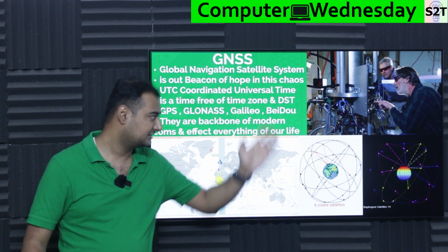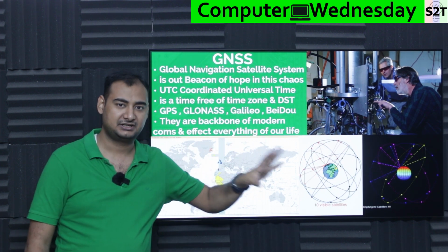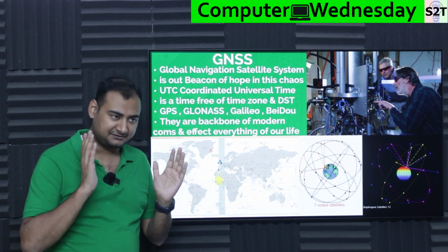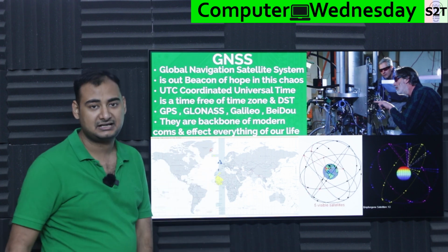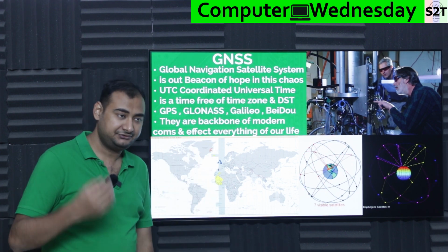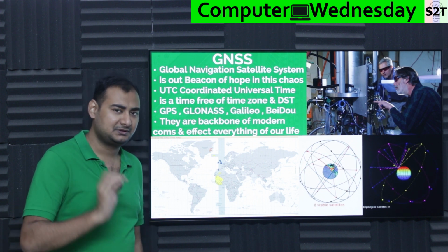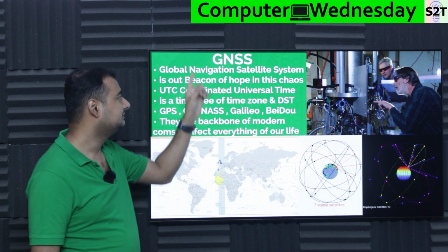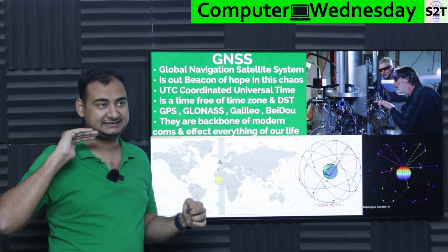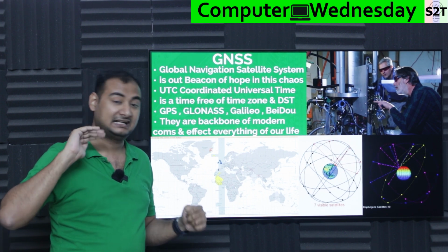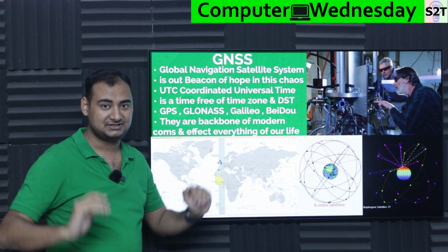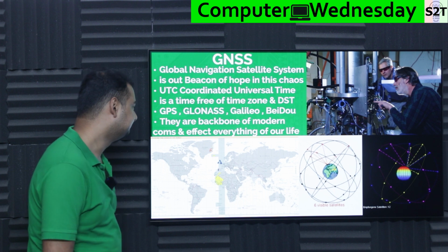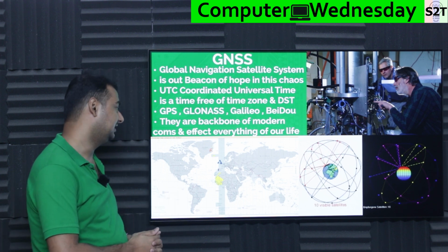So how do we transfer the standards? Basically, these super duper hyper accurate atomic clocks, in every nation, all these 4 nations, they work their ass off to have the most precise time, send their time to their satellite system, and that's how it's distributed around the world. So if you have a GPS receiver, you are getting direct reference data. And for time calculation, GNSS data is classified as level 1. This is level 1, level 0 is like, this is the time. If you are going below the resolution that this puppy can provide, at that point you are at research level.